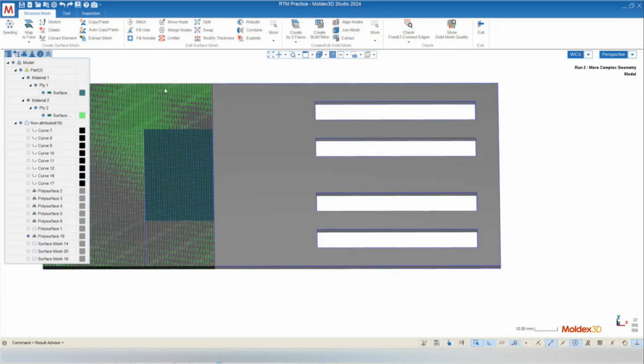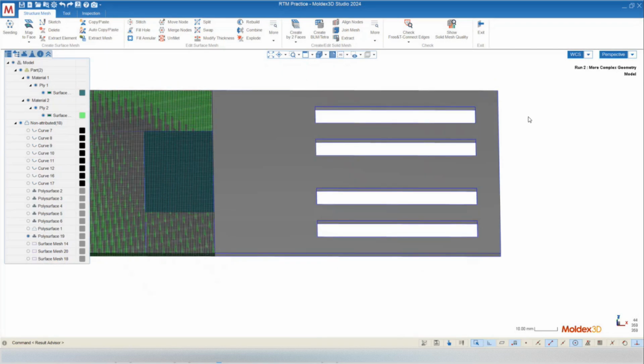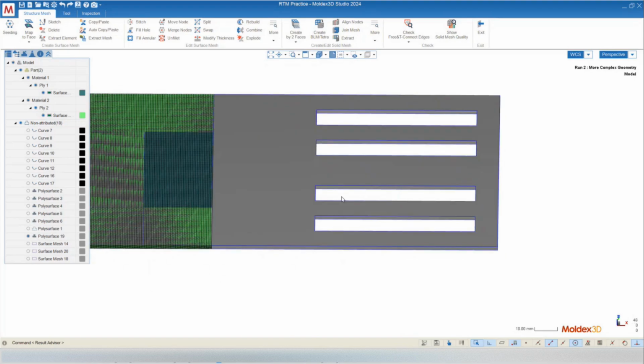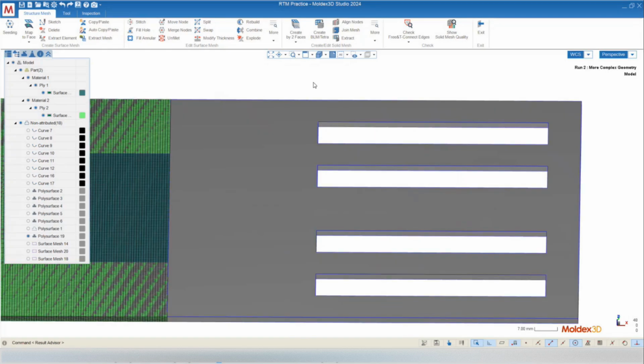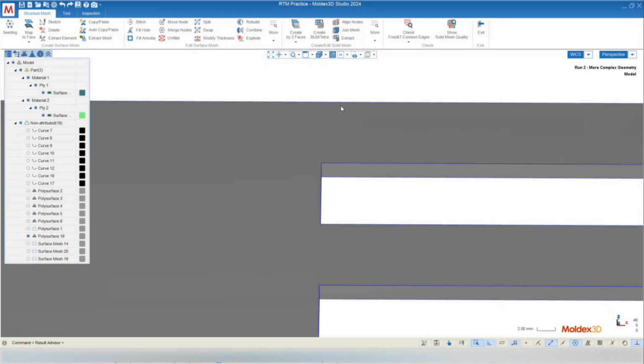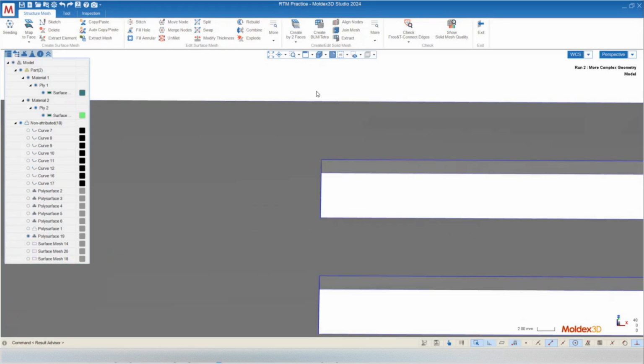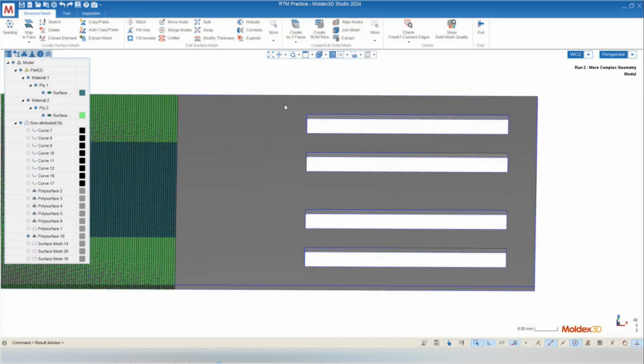All right, so in a similar way to how we created the isolation over here, we'll create some lines, and then we'll divide the face based on those lines. And the nice thing is for this geometry, because they're kind of all in the same line, we pretty much only need one line to divide the face. We just need to go from here all the way. But we're actually going to have to create 2 lines because there is no reference that occurs right here. So we have to first create that reference, and then we can draw the line.